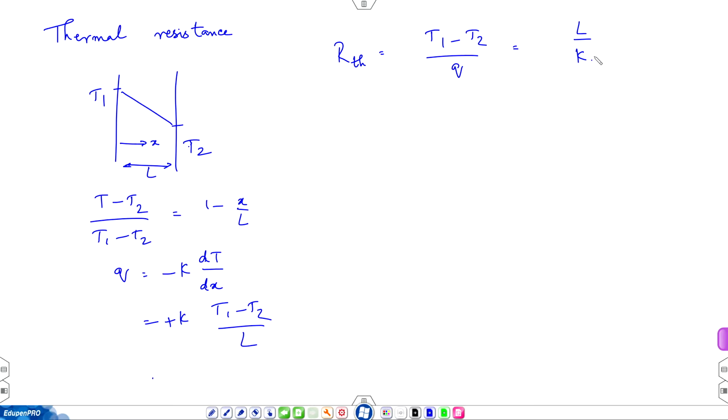Thermal resistance network is similar to electrical resistance network, mainly because the resistance is constant, it is a linear problem. You can construct a fluid resistance network also, but it is harder to solve because resistances depend on flow rate. So, you have that trial and error procedure to be adopted. So, I want you to complete this problem.